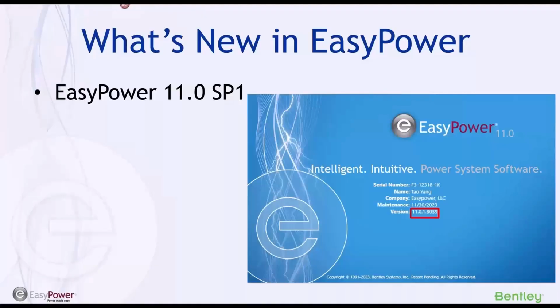But unfortunately, we introduced a bug in the IEEE 519-2022 calculations, which has been included in the release notes as well. So we fixed that immediately. I found it when I was about to prepare this webinar. Sorry about that again. So be careful to use EasyPower 11.0 Service Pack 1. Specifically, if you launch EasyPower 11, you should check that your version is equal to or later than 11.0.1 ATS39, your subversion. Make sure your EasyPower version is later than that. The bug was introduced because the second harmonic order was not taken into consideration, and I found out and immediately put out a service pack when I prepared the material.